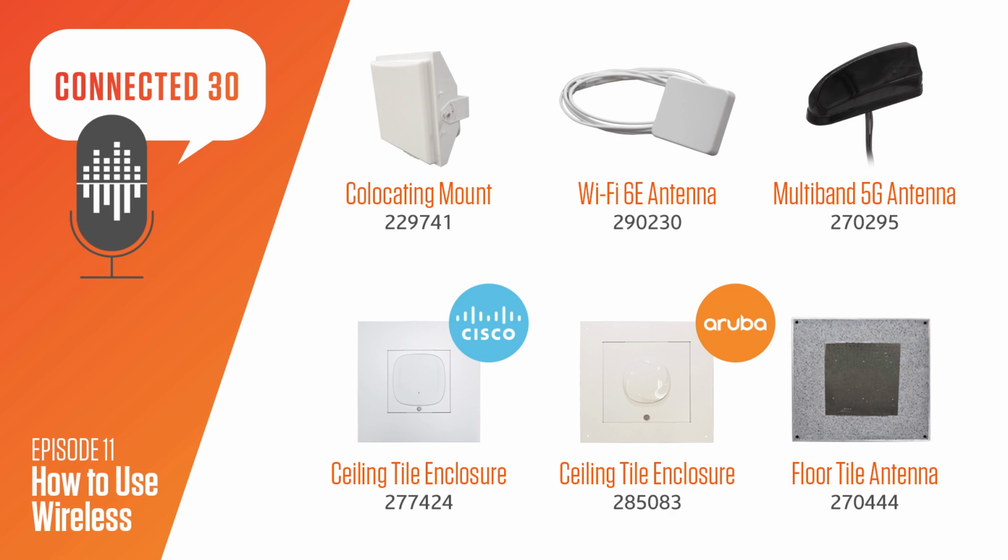So when we're talking about Wi-Fi 6E, let's go back and detail what the different types of devices will be in 6E. What we have is low power indoor devices. These are the devices specifically that have internal antennas. With these devices, the EIRP, or effective isotropic radiated power, is 18 dBm at 20 megahertz, which is the channel bandwidth, 21 dBm at a channel bandwidth of 40 megahertz, and 24 dBm at a channel bandwidth of 80 megahertz.